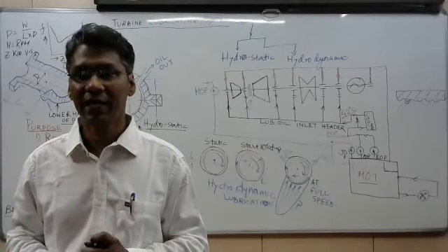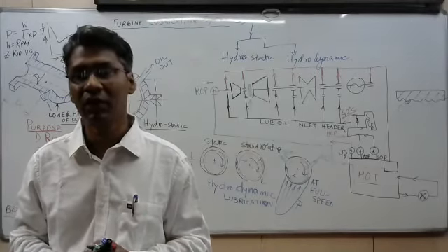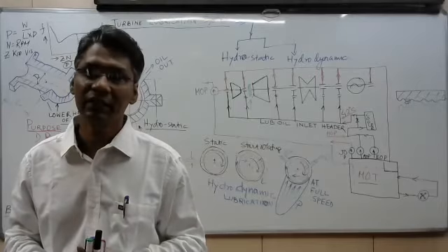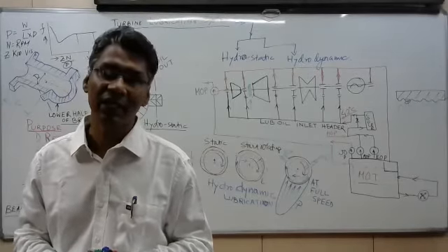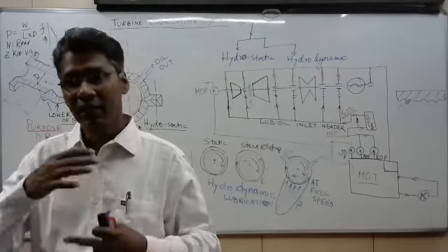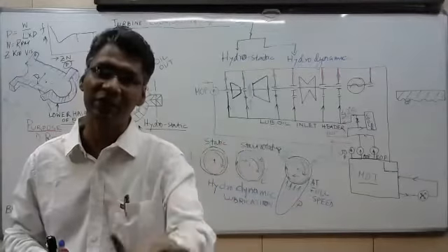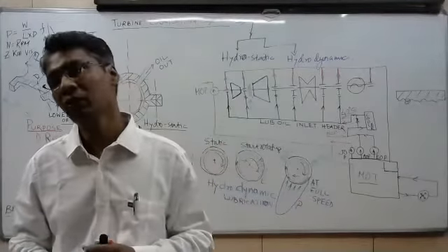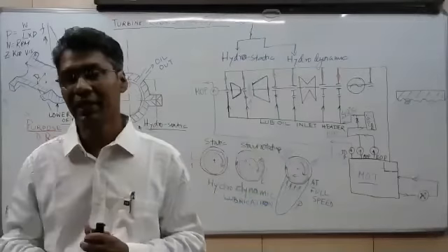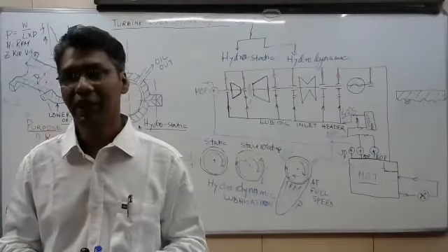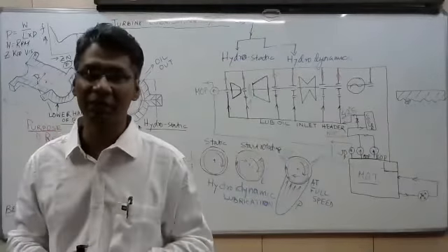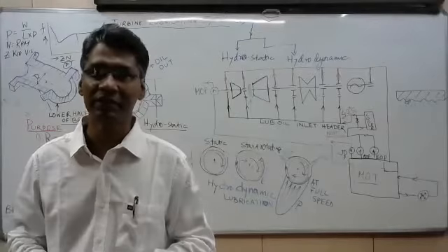Saurabh Chatterjee asks, will that high pressure be enough to lift the rotor? Obviously, we design the bearing in such a way that the oil film is capable enough to lift the rotor. Otherwise, it will not run. It will be damaged within minutes. If it is not lifting, it will be damaged.